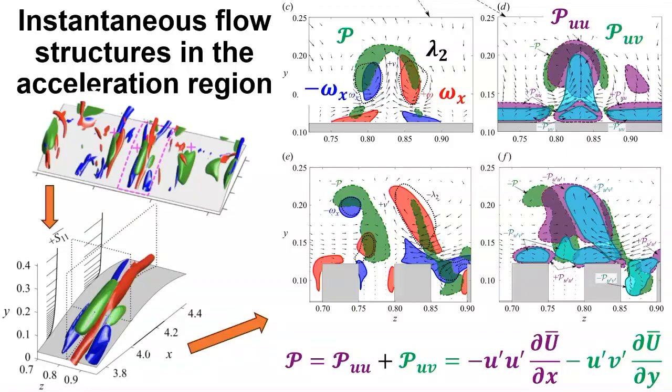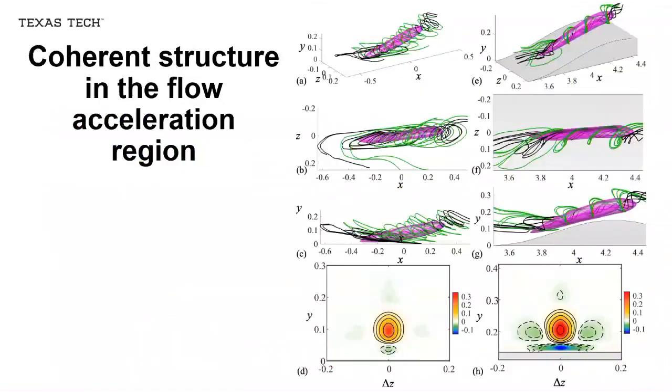Here is a cross section of this dipole, and the negative production always occurs on top of these dipoles. So it is the dipoles that are responsible for the generation of this negative production you see happening very often in the flow. There are many more details I will not go into, but those dipoles, prevalent in the accelerating part, are the origin of this negative production.